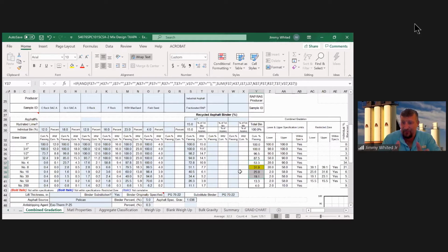You're going to have a good QC department. You got to do your research. Each mix is going to be just a little bit different than the other mix. But once you do this testing and pull this data in and make a major change in a day where you can see what's below this or what's right above it, as soon as you get into that really good number on that number 8, and you lock it in, you're going to maximize your densities and you're not going to see any fluctuation.